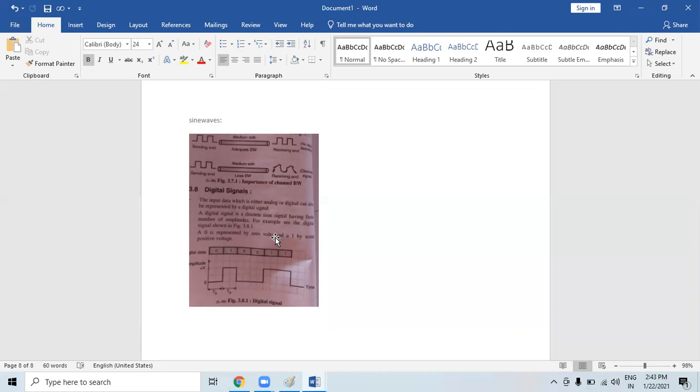The range of frequency that contains the information is called channel bandwidth. The term channel bandwidth is used to describe the range of frequency required to transmit the desired information. For example, an amplitude modulation system needs a channel bandwidth of 100 kHz to transmit a signal of 15 kHz bandwidth. But a single sideband system needs only 5 kHz channel bandwidth to transmit the same signal.